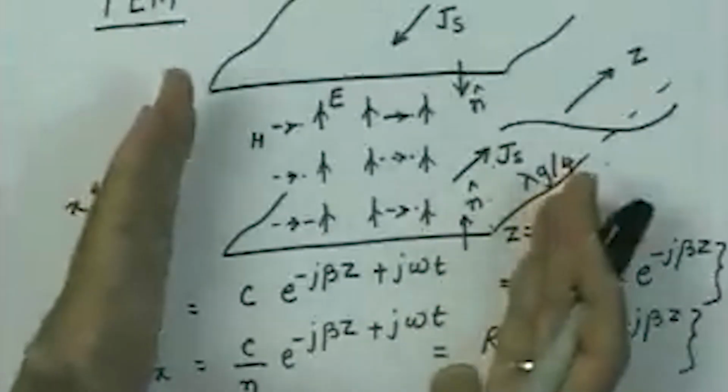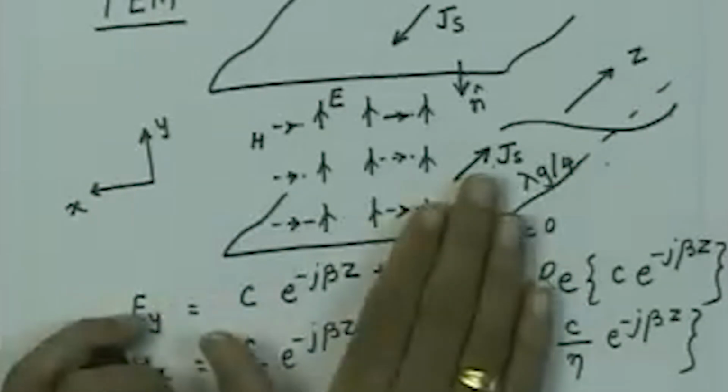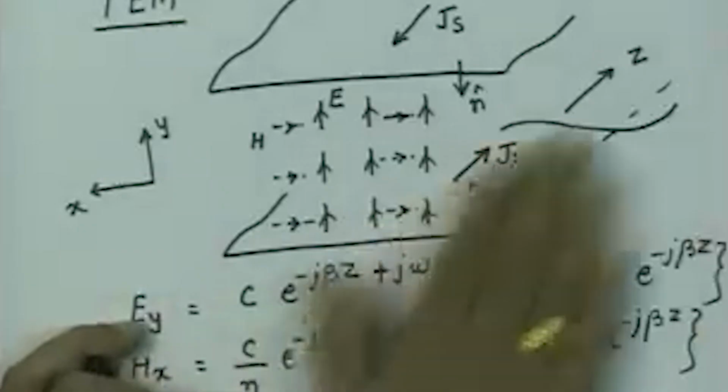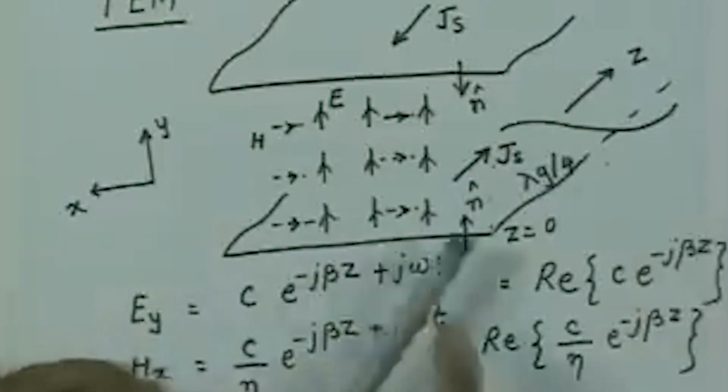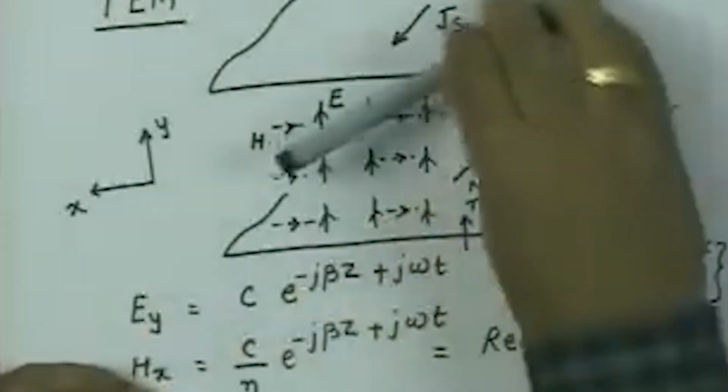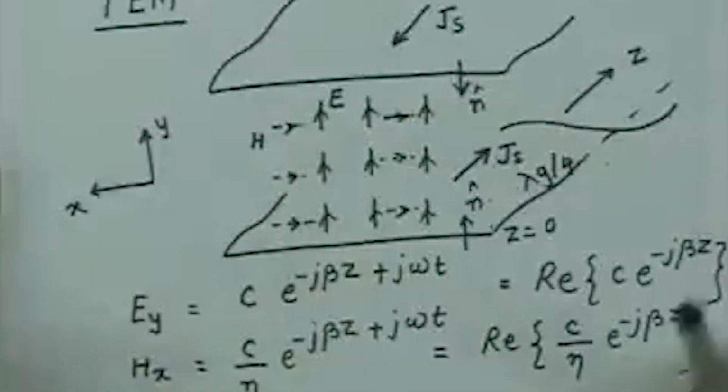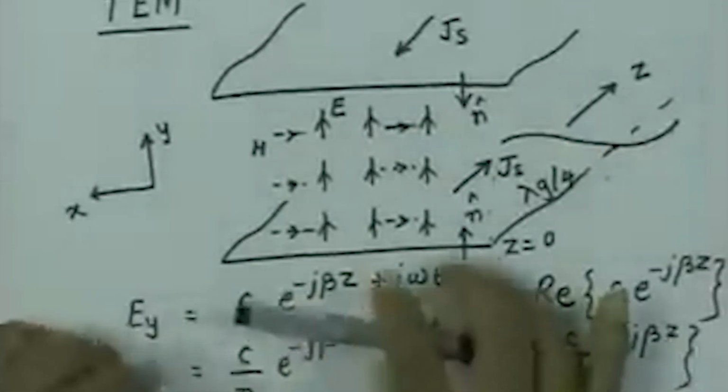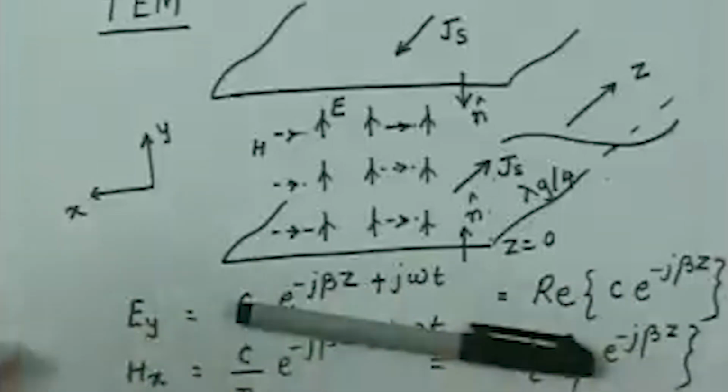So, in a two conductor system, it gives you the current flow in the direction in which the wave is propagating. I have a current flowing this way, I have a current flowing this way, and precisely that is what we are used to, that when we have a two conductor system like a coaxial cable, we connect a voltage source and the current goes inside the conductor, the current returns by what is called a ground path.